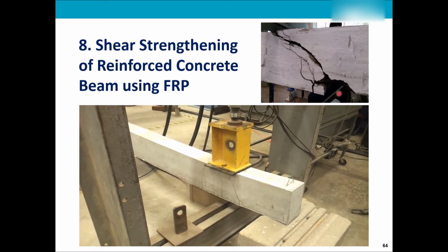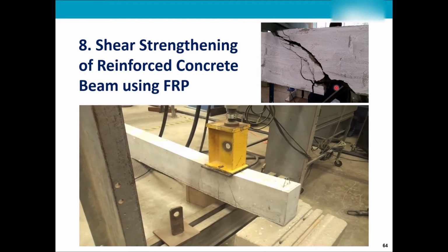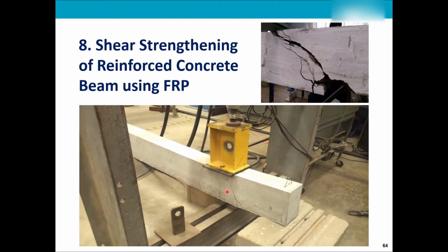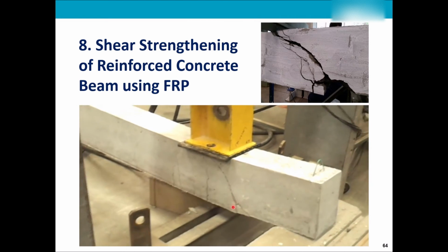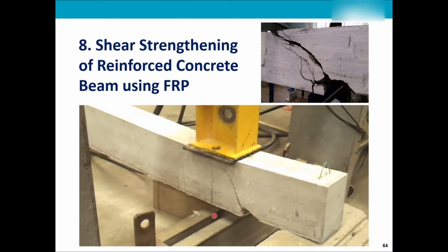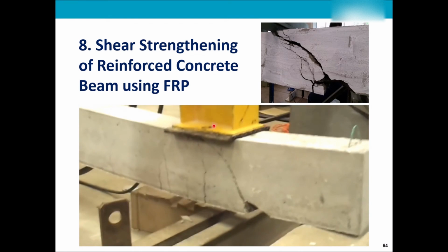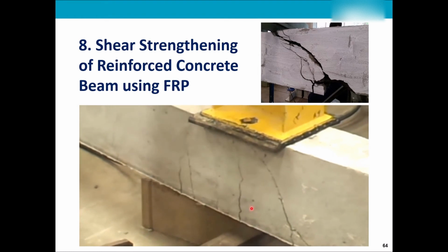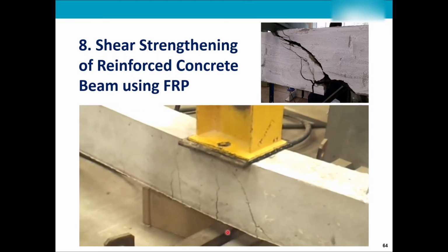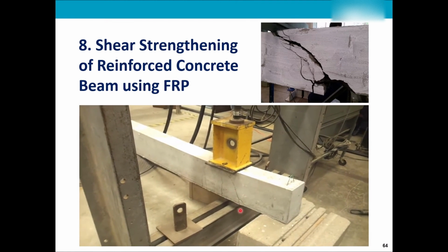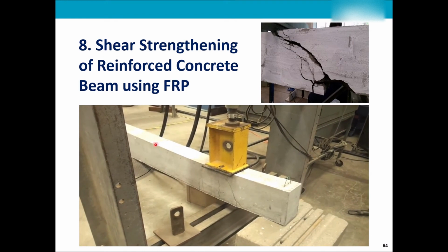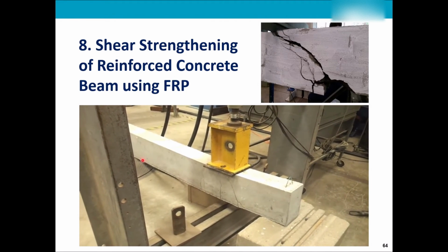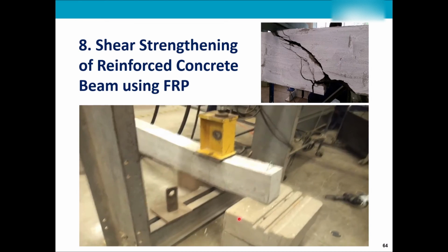This is a good shear crack that you can see in a concrete beam. In this experimental test, we're just applying the load at the side, so you can see a proper crack going from the bottom to the top or from the top to the bottom, which is shear. It's not due to the flexural. It's very close to the supports. If you remember, the bending and the flexural is usually away from the support and in the middle because the beam bends. The shear usually is in the sides.